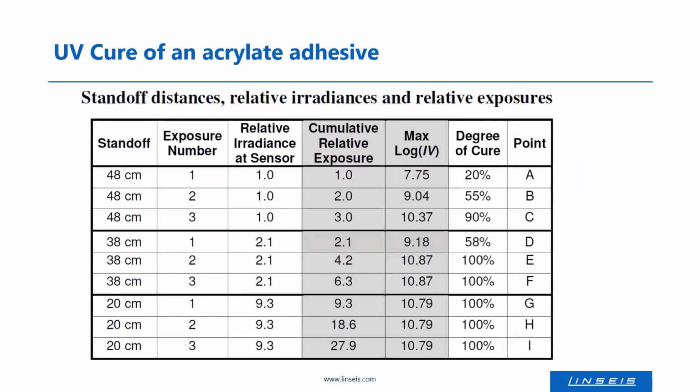possibilities. And at the end of UV studies with the dielectrical analysis, you get figures like shown here in that table. You see here the degree of cure, which you can calculate from your curing curves as a function of the intensity of the UV light, of the exposure numbers with the UV light, and the distance of the light source to your sample.